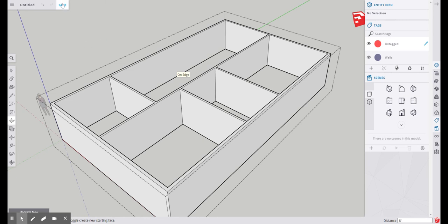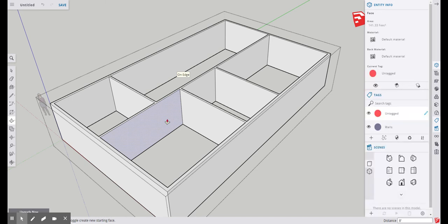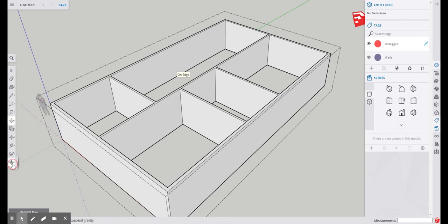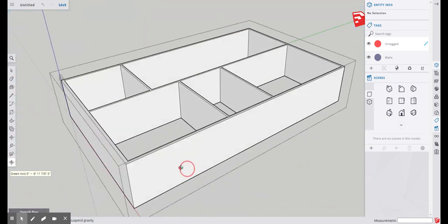That definitely saves time, but let's say you accidentally made the exterior walls 9 feet. Now your entire building would be incorrect, because you said you wanted it the same height as this. So it's really good to make sure you measure things, because it happens. I could have accidentally made this 9 feet, but thanks to the measurement tool, it's confirming that it's 8 feet. There we go, there are our walls.